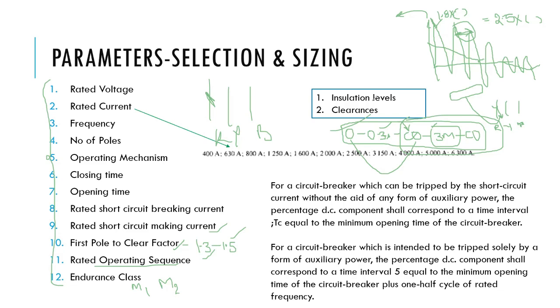And one more important thing here. In the breakers we always have two coils. One is a tripping coil, the other one is a closing coil. In the specification, we again specify some additional things for those coils, like the coil should be designed in such a way that the tripping coil operates for 70% to 110% of the voltage.